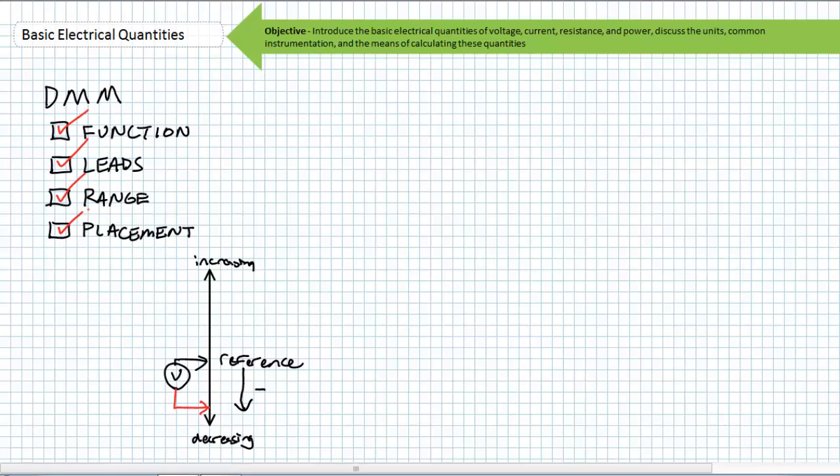For now though, let's keep it simple. And let's say that any source I draw is an ideal voltage source. And if I say I'm using a 12 volt ideal voltage source, between its terminals, we should see a difference of approximately 12 volts. Regarding the meter, be aware that there's a limited range meters can safely measure. Most of the time it's written on the back of the meter or affixed to a sticker somewhere. Do not exceed this range or you'll damage the meter and yourself in the process of doing so.